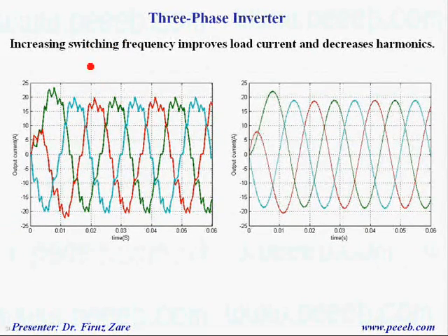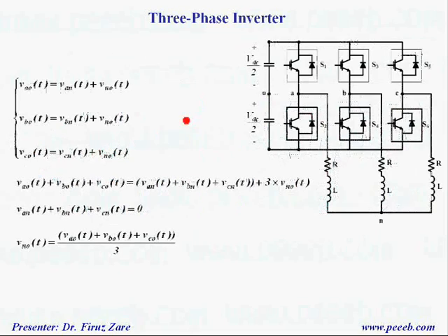So what's the effect of switching frequency? Increasing switching frequency, we can improve the current and reduce the harmonics, but a drawback is increased switching losses.